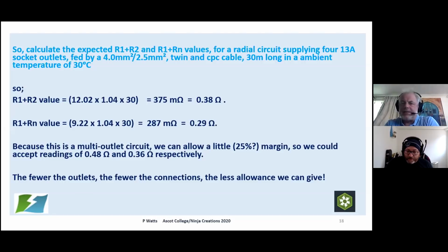Yeah, plug-in leads. The plug-in socket type test lead is so useful and it saves you so much time, but we've got to be aware of the fact that sometimes it can give us a very poor contact. Yeah. And there's many a time where I've been putting sideways twisting pressure on a plug on a test lead, trying to get a good contact on a socket. And the other thing is the actual switch on the socket.